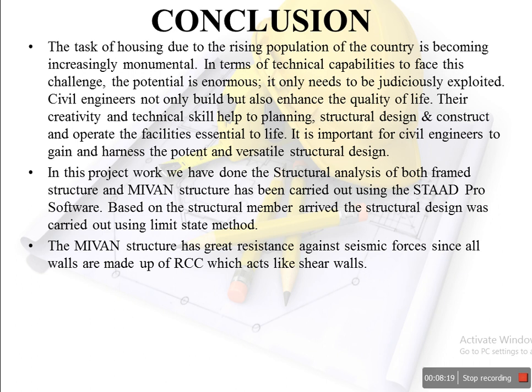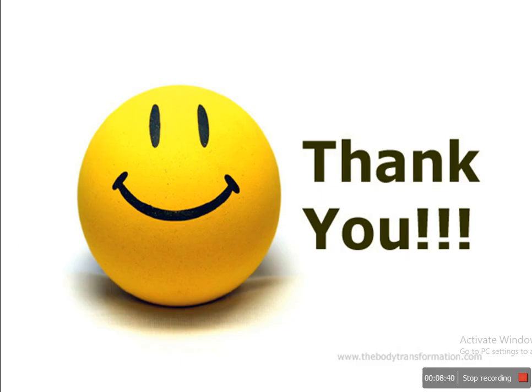In this project work, the structural analysis of both the framed structure and the Mivan structure has been carried out using STAAD Pro software. Based on the structural members arrived at, the structural design was carried out using the limit state method. The Mivan structure has great resistance against seismic forces since all walls are made of RCC, which act like shear walls. References. Thank you.